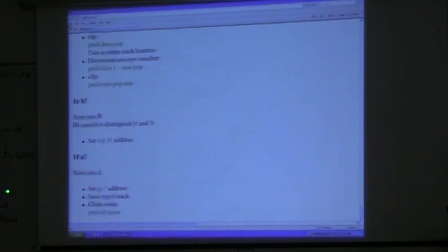If you really want a clean swap, the nicest way of doing it is push A store, pop A. But that does require that you have used the return stack location and you've destroyed A. So you'd like to avoid that. And so there we are, 33 instructions, the 33rd being add with carry.